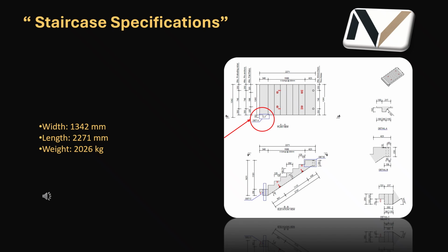Like the previous one, it has three stages for QA checking. First, after the mold is prepared, the angles should be checked, the goings, the nose to nose dimensions should be checked, and the waist of the mold should be checked. Embedded items should also be checked. So we've got protruding rebars.